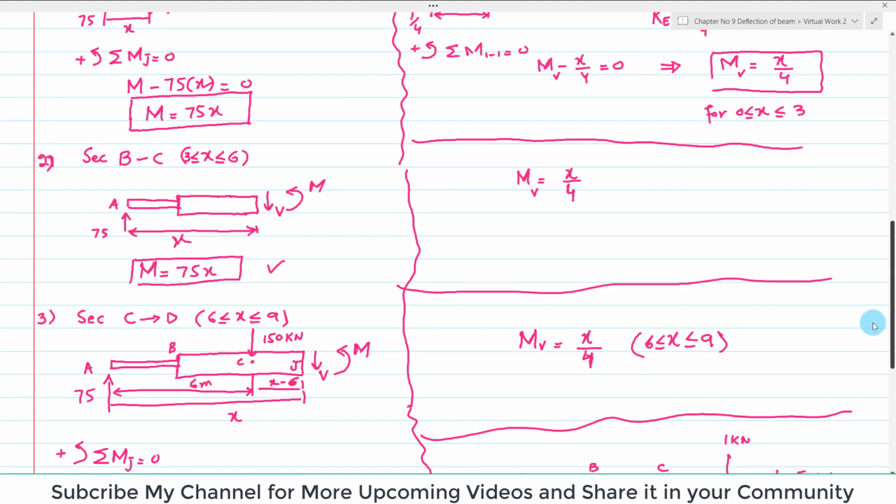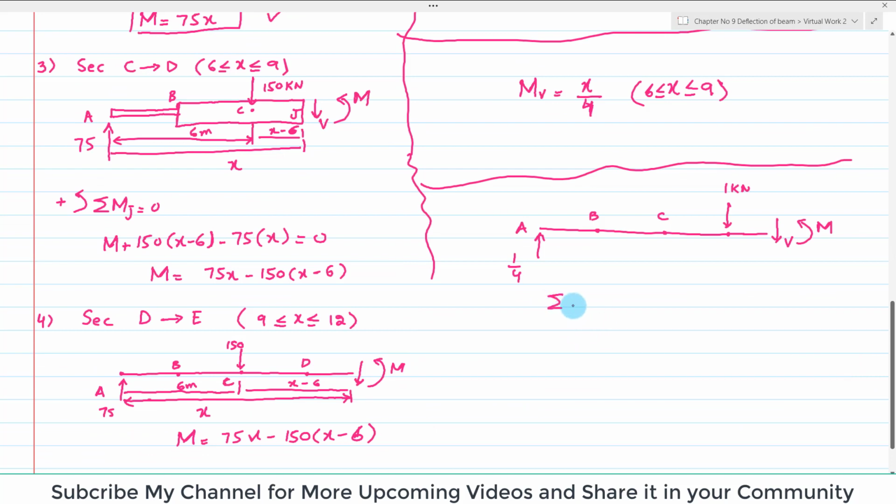And this was section 4.4. So we will calculate the sum of all moments about section 4.4 equal to 0, taking counterclockwise as positive. Let the distance where we cut the section be x. Clear? From A to point D, this distance was 9 meters, because the distance between each segment is 3, so it is 9 meters. Clear? So this distance will be equal to x minus 9.